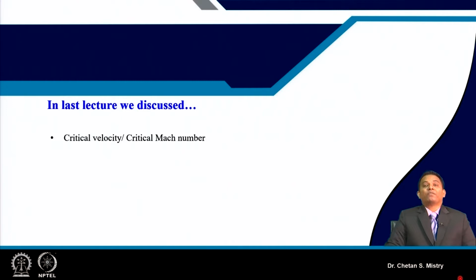Based on that, we need to decide what will be the diameter of my casing, the diameter of my hub, the height of my blade, the chord of my blade, and how my flow angles will be varying. We have different approaches for the design of the blade from hub to shroud, and that's how we do our iterations, and finally we reach some shape of our stage for rotor and stator. That is what we have defined as a sizing problem.